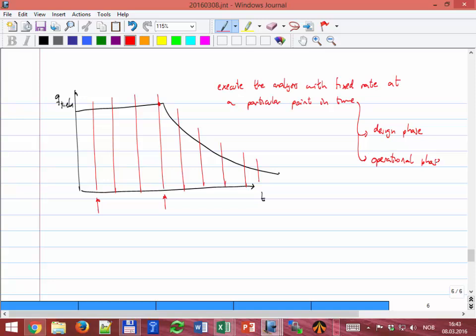So we take out all the complexity. If you go to a flow assurance engineer and say coupling, reservoir simulator, which reservoir pressure are you using, they're going to think this guy is crazy. Why is he talking about all of these things? Because they just don't care. They look at one point in time: I know how much I'm producing, I know what my rate is, and then I impose it on the pipe and perform my analysis, executing hydrates or wax or transient, etc. They don't care about interaction, flow equilibrium, well performance, etc. Any questions?